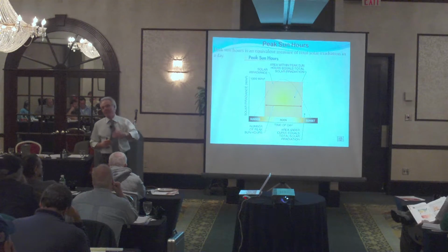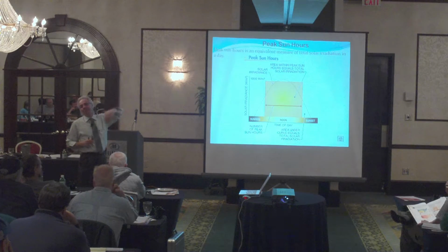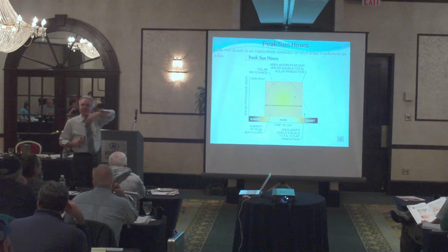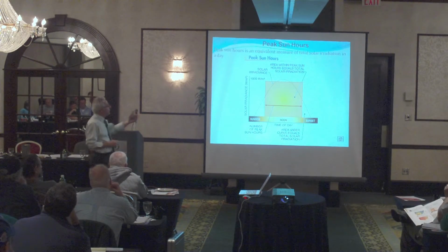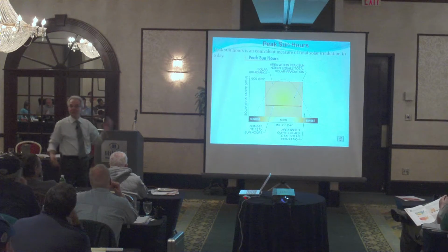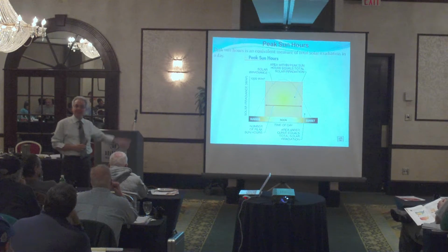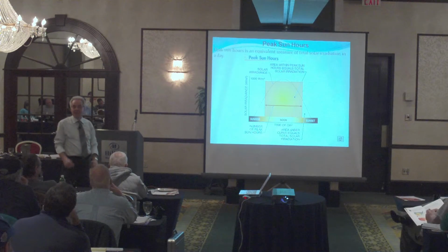It's actually tabulated for you because they have taken data from the 1960s, I think, up to 1991. To come up with a number, you want to make sure to take enough data and tabulate it, accounting for deviations of weather conditions and so on, to come up with the average. So the average for New Jersey is between 3 and 3.5 hours of peak sun radiation.